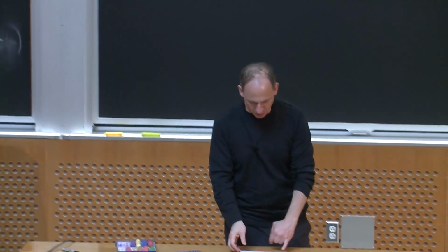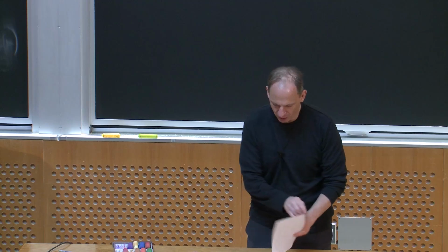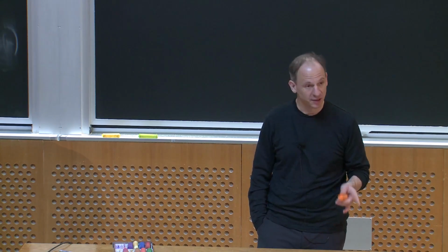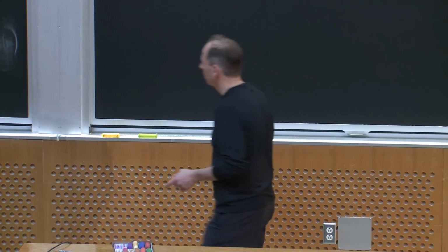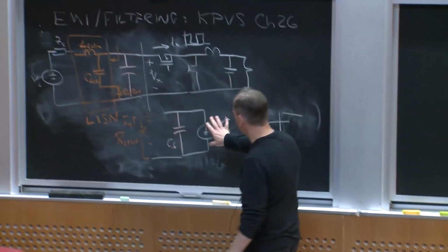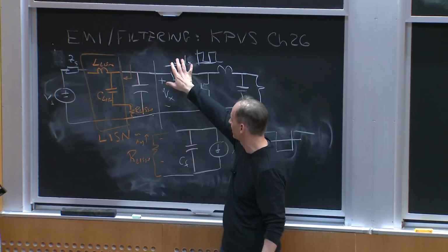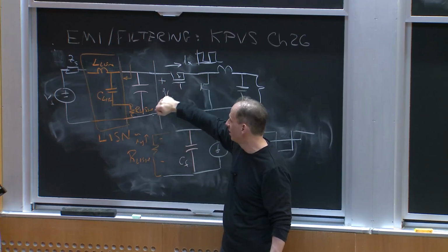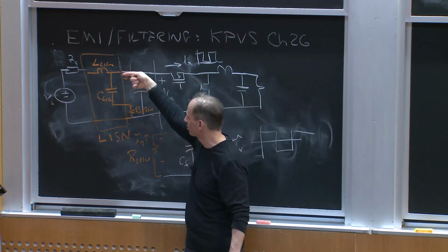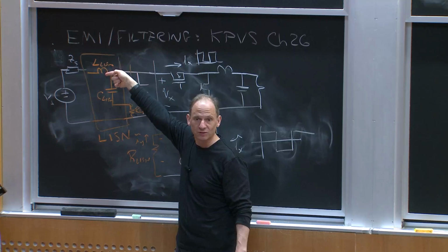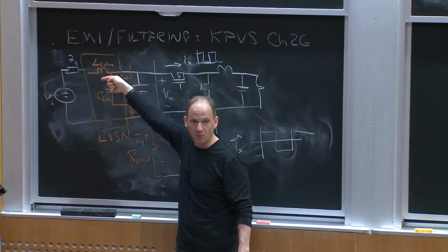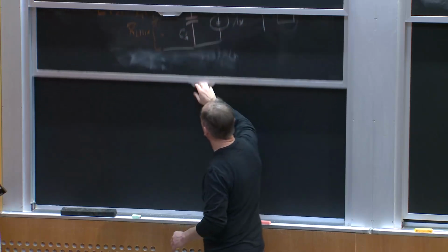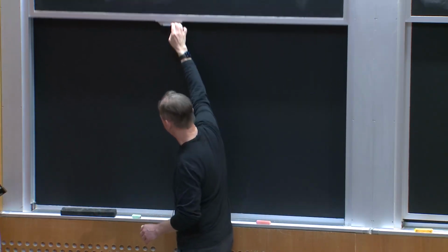So we said, okay, we need to design a filter here. A capacitor is not going to cut it because, for typical specifications, who knows what this is? Maybe this is tens of amps. Typically, the current I'm allowed to squirt back into here is on the order of tens of microamps. It's really small, so we usually need to design a higher order filter than that.